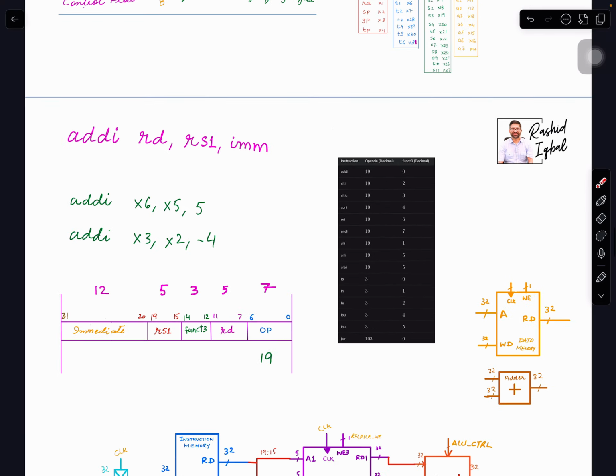We will work out what kind of binary or hexadecimal value belongs to this instruction, but let's look into this. Once this 32-bit value comes here, independent of what value is actually there, we need to create an architecture which works for anything, right? It reads this as a source register, it reads this 12-bit value, then adds these two values and puts the output in the destination. Correct? That's all we want to do.